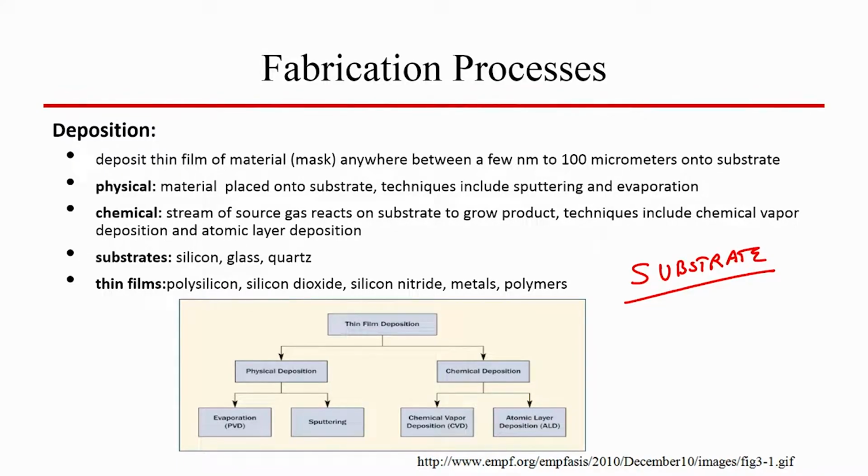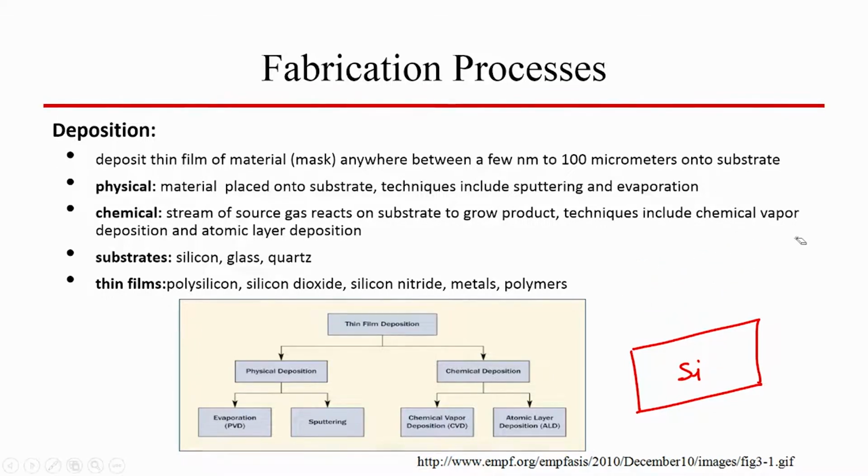Now, let us say you want to fabricate a heater, right. So, you have a silicon wafer. If I have a silicon wafer, can I deposit a metal directly on the silicon wafer? No, because silicon is a semiconductor. So, I have to have an insulating layer. This insulating layer is SiO2, alright, and then on that we will deposit a metal. This metal is nichrome, right. Nichrome is a material that you use for fabricating the heater.